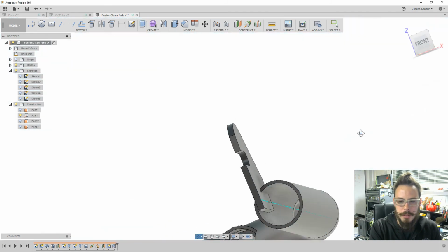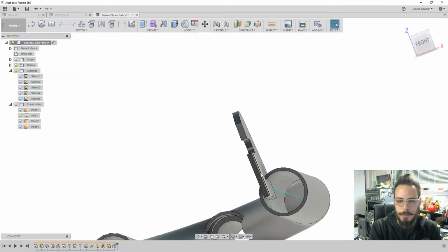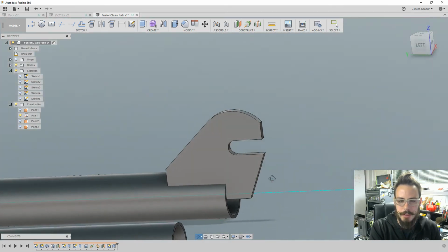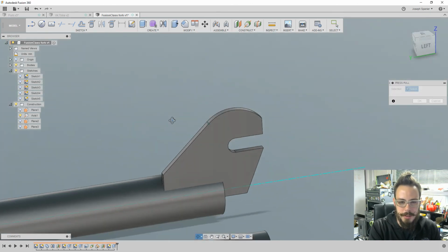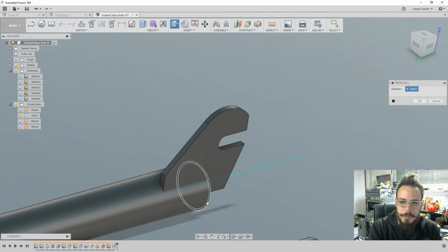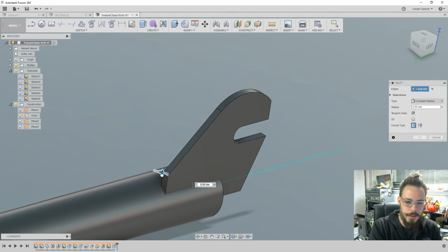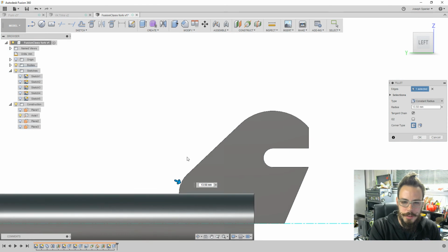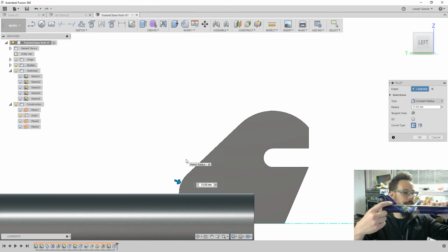Click OK. So now we have this new fork plate thing in here. But it looks pretty rough, and I don't really like how it looks. I want to round things out because this is CAD, and we can. So I'm going to click press pull, and we'll click this line here, and I can just push this fillet in until it looks somewhat like this radius here.